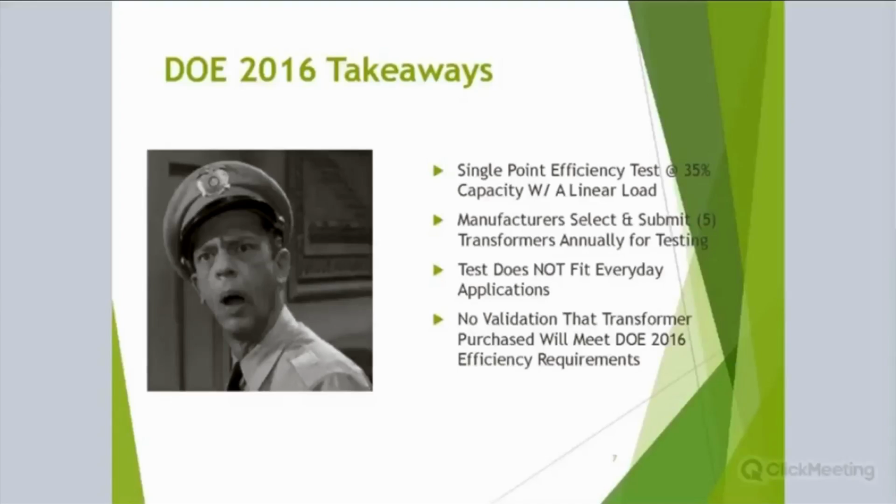The test does not fit everyday applications, meaning you don't have a test that really shows you what you're going to see in your facility day one through the end of its life. And then there's no validation that a transformer will actually meet the DOE 2016 requirements, meaning there's no test to prove that the unit being shipped to your facility meets the requirements.